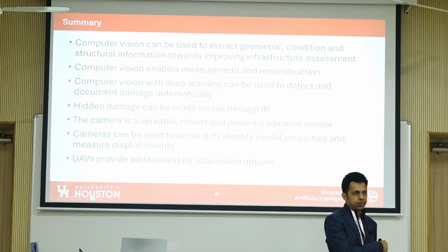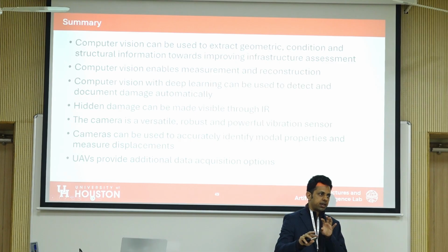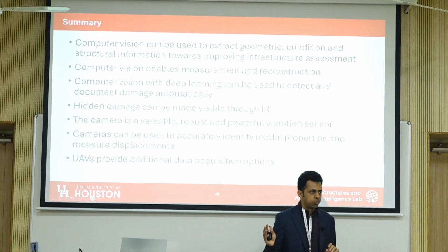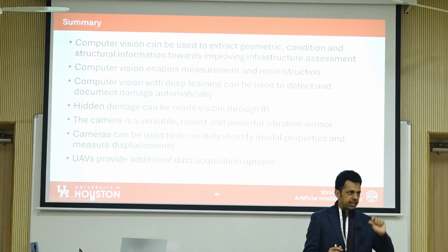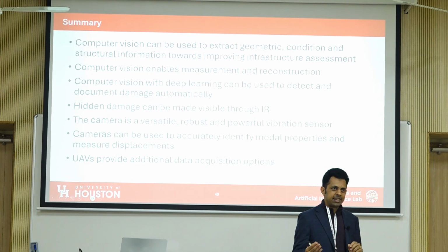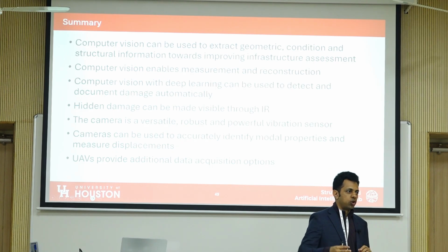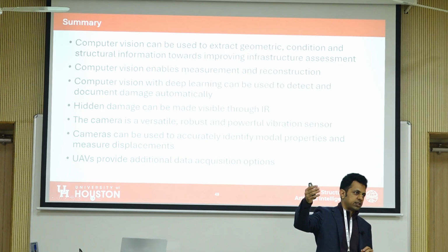and then you incorporate that into the camera matrix. We'll see the camera matrix after lunch, which gives you the location of the camera with respect to the world and the properties of how the camera takes the world coordinates and transforms them into image coordinates. So we'll look at that in more detail. But you can get the displacement of the camera, incorporate that into your camera matrix, and then you can get the displacement that you're measuring. But the challenge there is that sometimes, or most times, it's hard to find a stationary point if you're trying to measure civil infrastructure that's vibrating.